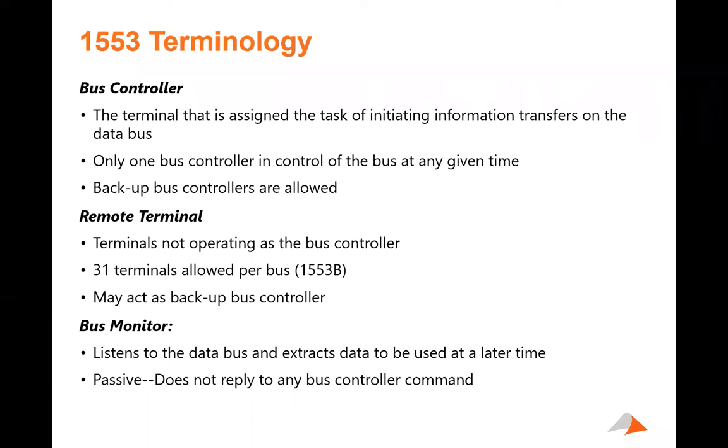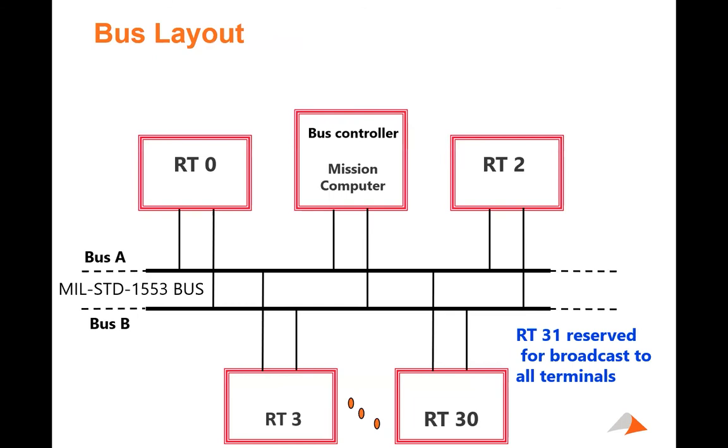And I've been on a number of strangely installed 1553 data buses that if you connected anything on them, it would go down. So a passive one can be very nice. I mean, absolutely a high impedance one. So anyhow, again, monitors do nothing but listen. Any questions?